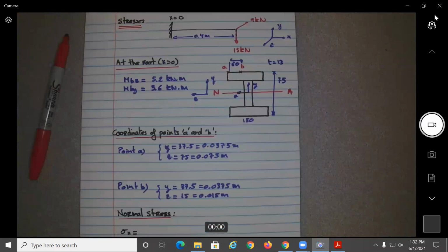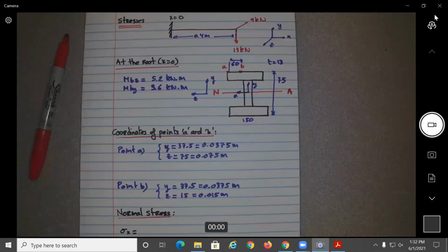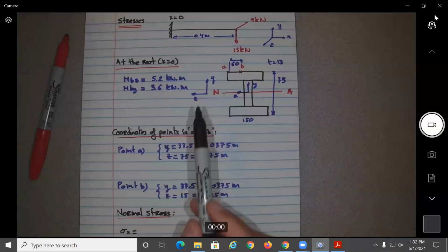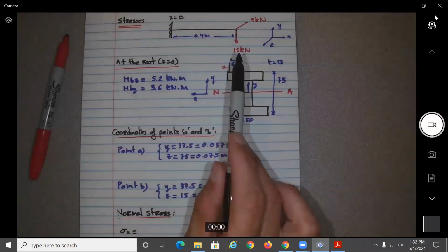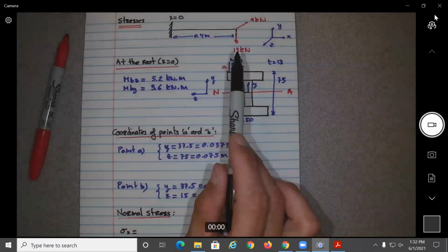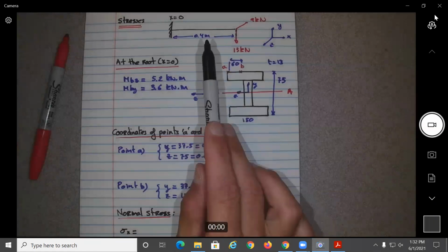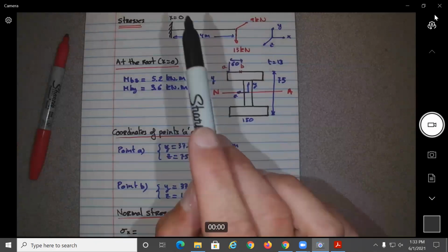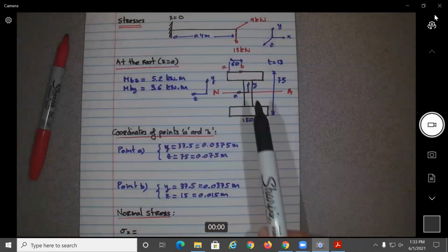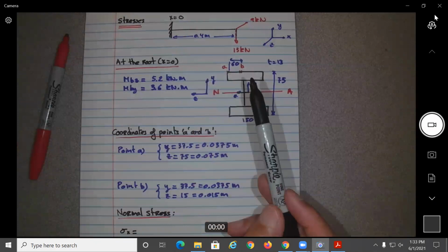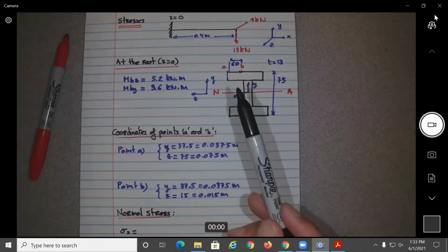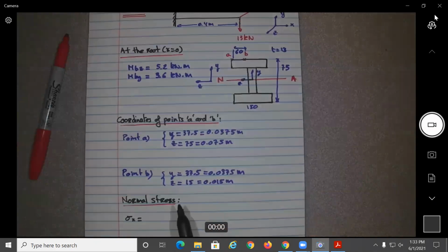Okay, and if we look at the figure on top, you will have a normal stress on the X direction due to the moment created by this 13, which is 13 times 0.4 will be the 5.2, which is this one. So this one will be going down, no? Yeah, this cross section will be bending. So will point A and B be in tension or compression? Will be in tension. So we can write over here tension. So we know that should be negative.